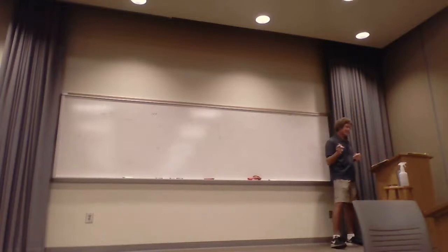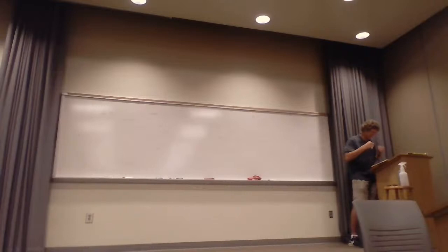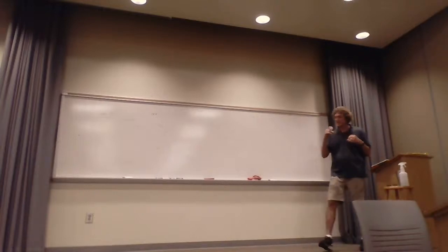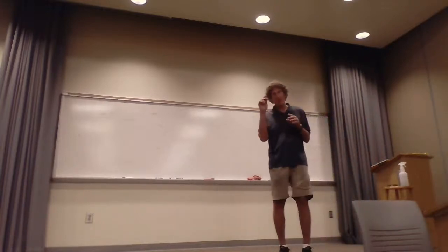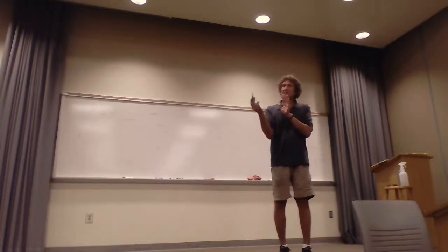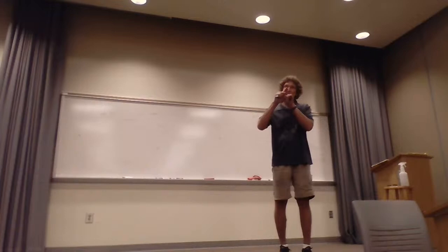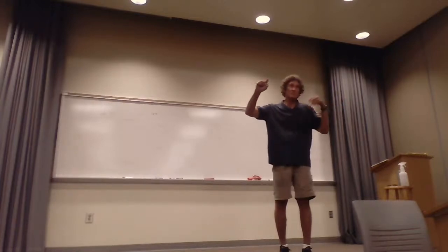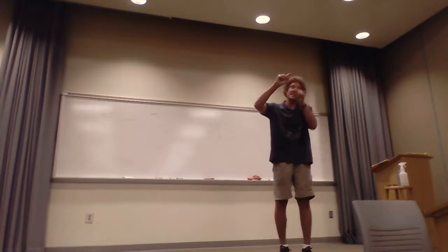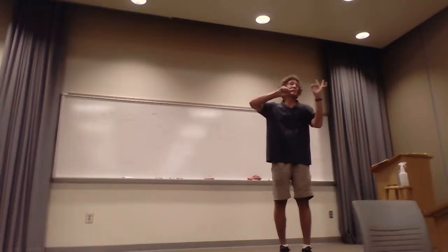It means, and this is the odd thing, for the 0th mode, I think he says there will always be a TM0 mode, all right? You see that at the very top of page 404, well, he doesn't even show a 0. You know how normally it's like TM10, or TM11, something like that. Well, the reason he's not showing the second one is the second dimension is assumed infinite. Right? So those mode numbers have to do with how many half wavelengths are between the top and the bottom and cutoff. Here you have 0.